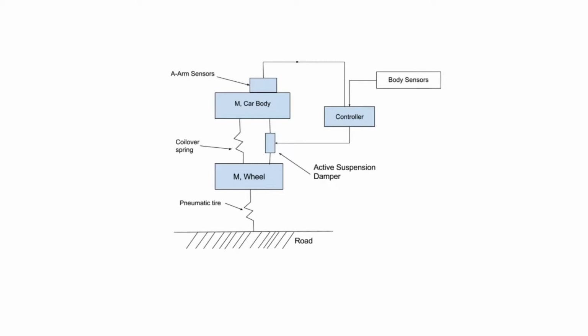This is a schematic of the dynamic system as it is represented in the car. We can see all the components that go into the suspension system. Inputs from the suspension and the body contribute in creating a system that is stable. To help mitigate the effects of body roll, engineers created a system that, upon turning, braking, or acceleration, the suspension dampers located on the outside of a turn stiffen and allow for a proper response to a turn.